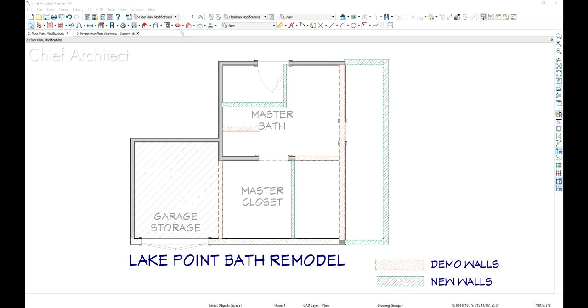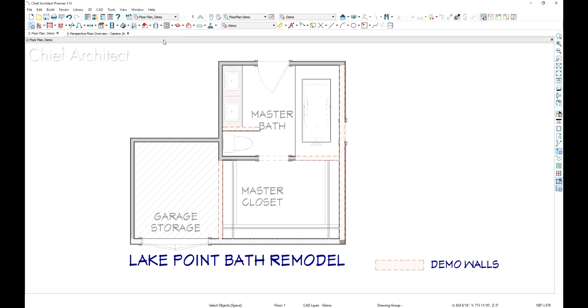Now as I switch back to the demo set, notice you don't see the modification walls. A little added detail of what just happened is when I drew those polylines, each one of these, if you notice when I click on the wall legend down here, the layer is actually on a layer called Demo. And by switching my default, when I change my layer sets, it then controls what you see on the Demo layer set and what you see on the Modification layer set.